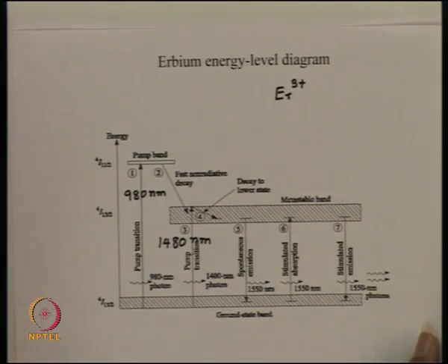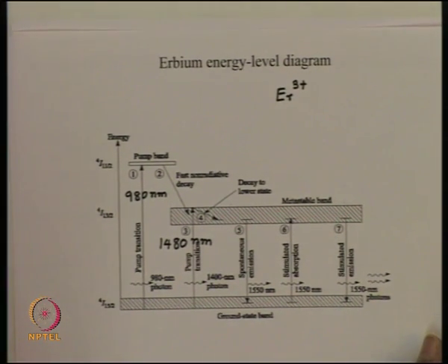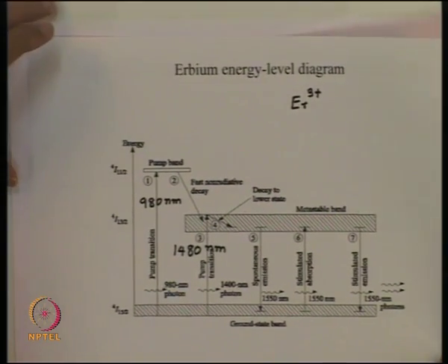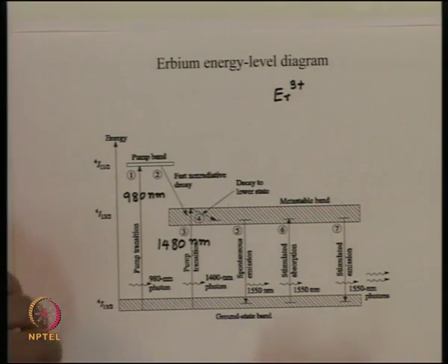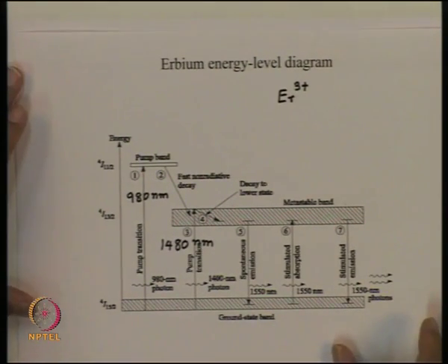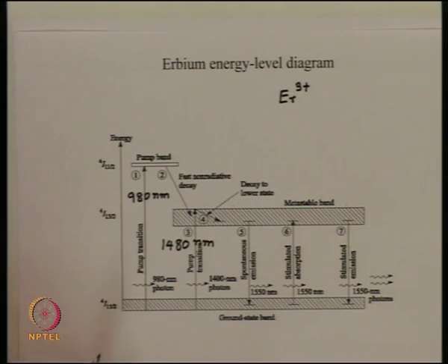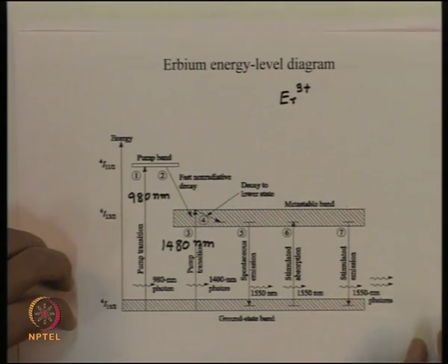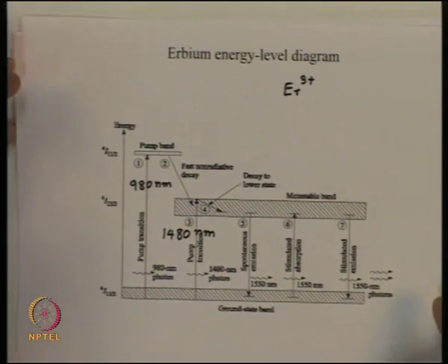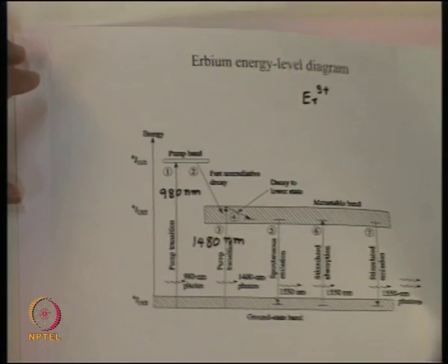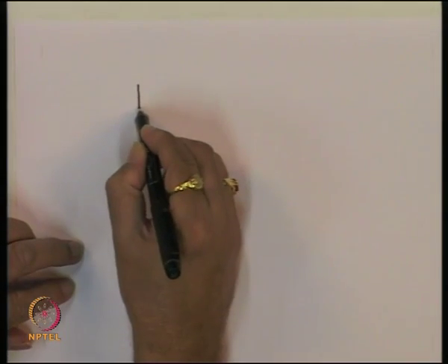So if you look at the characteristic of the optical amplifier, the gain depends upon the input signal power. If you take very low optical powers, minus 50-60 dBm, the gain is rather large, but as the optical power increases, the gain starts dropping. If you look at the typical characteristic of optical amplifier gain, it will look like this.